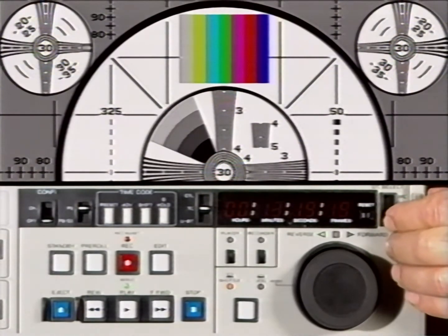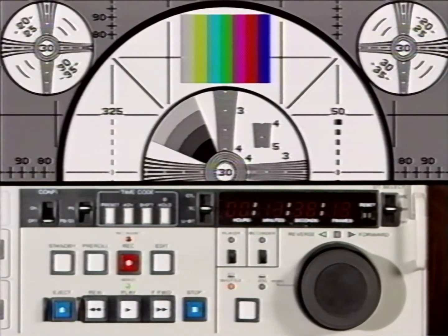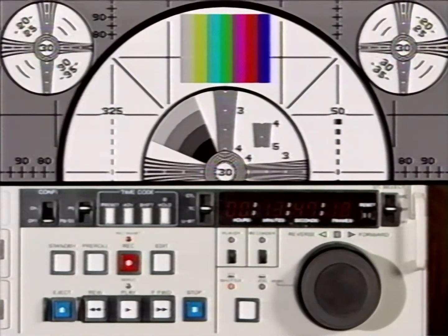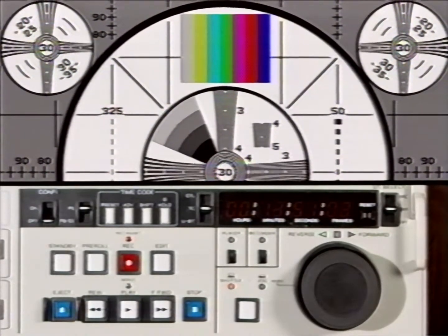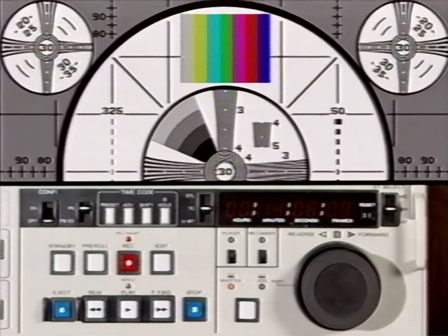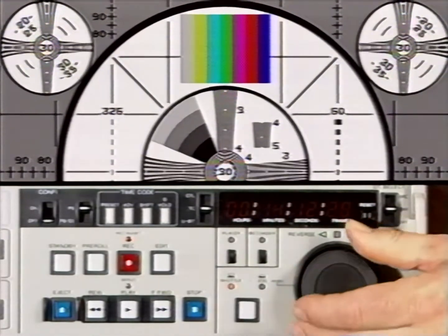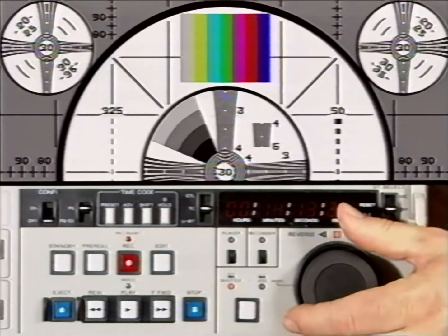When we switch from the record playback head to the DT head, and we misadjust the capstan free-speed control pot RV1 on the SV84 board, vertical jitter and loss of servo lock will result. Shuttling in the DT mode, with the unit still misadjusted, results in vertical jitter while the speed is changing, and the servo lock light remains off.